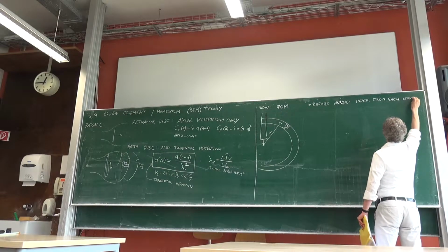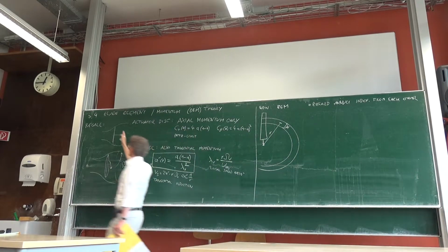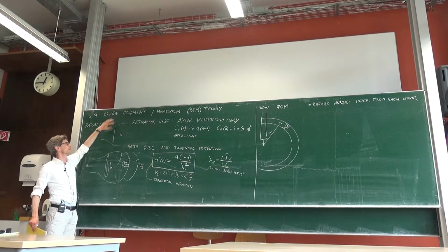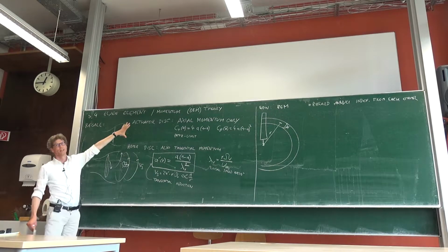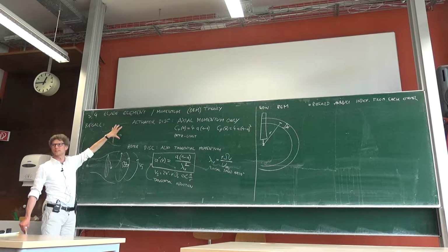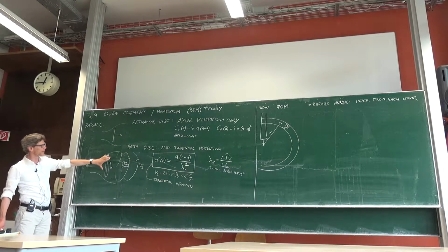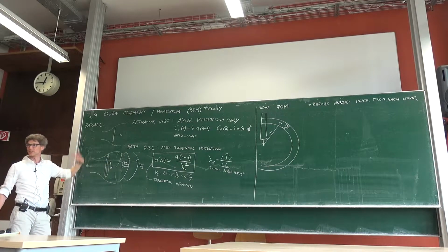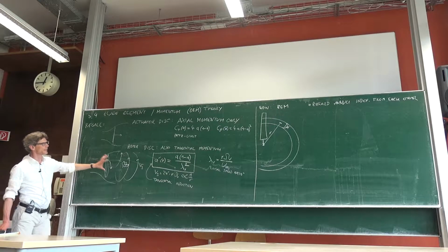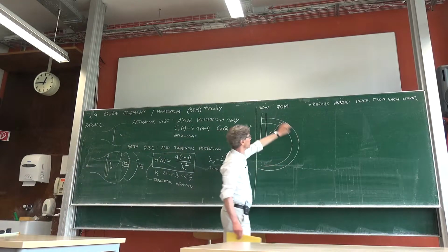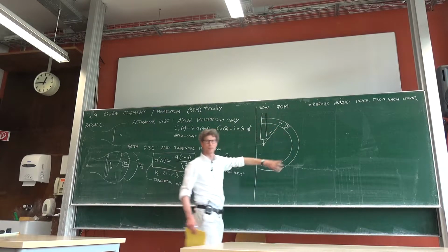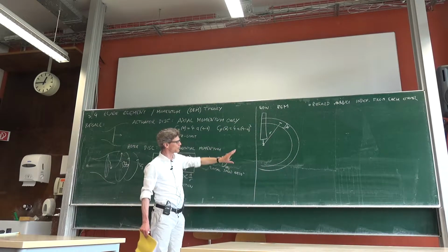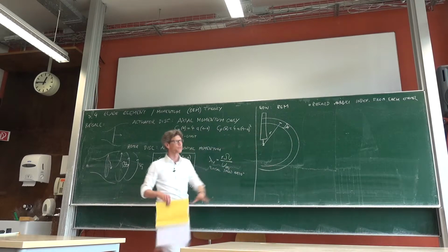Which is, of course, a very strong assumption, right? I mean, before we assumed here an actuator disk, we assume the flow in the middle is completely independent from the flow outside, right? Everything here is at rest and is flowing with a free stream velocity, and then here it gets slowed down in the stream tube. That was our assumption here. Here already we made the assumption that each annulus is rotating with a different speed. And they are completely independent, and this assumption we will also make now. So the air that flows through this part of your wind turbine is, so to say, completely independent from the air that flows through this part of the wind turbine. And this air will be slowed down, and it will get some tangential velocity.